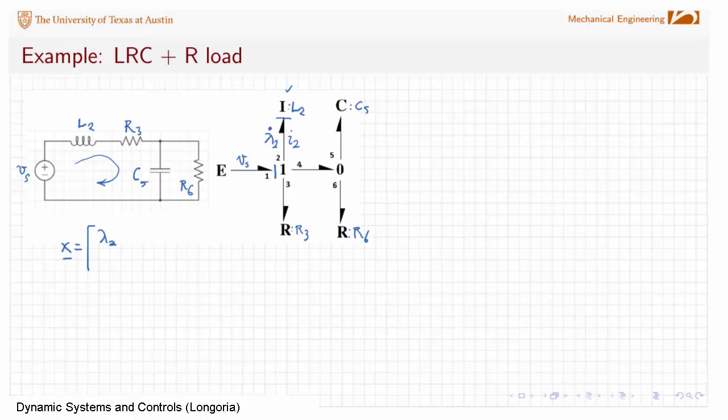And now that I've specified flow at that one junction, all of these have to be efforts onto that one. Okay. The voltage across 3 here is that resistance, is that voltage drop across that resistor there. But I3, the current through there, obviously is equal to I2, and so on. So sometimes I don't fully annotate the graph because, for example, here on this one junction, I know all these currents are the same. Unless you just want to put it down there for yourself, you should know that on a one junction all these currents are the same. There's no sense writing them all down.